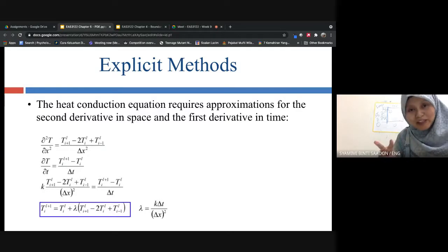we have two methods, explicit and implicit. First, the explicit method. This is the equation, just like the Laplacian equation just now. We have the second order partial derivative of T over x. This is the same, it's just that this time we have this unknown value L. L is the time, so time at L seconds, for example. So now we have two unknowns.